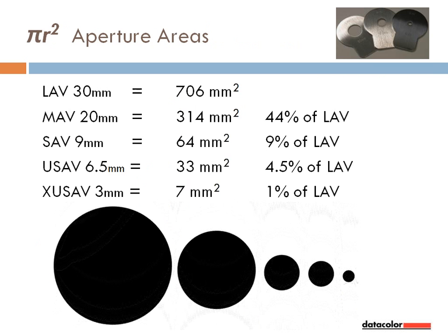Remember, a larger area measured is a more representative sampling. Avoiding aperture changes to save time can be a false economy. Notice that it takes 10 measurements using a 9mm aperture to give the same measured area as a single measurement using the 30mm one.